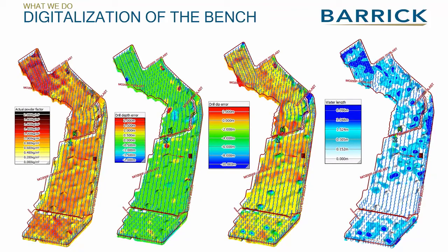And we also have a water surface of how it was on the pit. And as you can see, actually, we can have conclusions by seeing this. Between the blast, you can see that we have the less powder factor. That is because there is where the holes are more potentially falling. So with that, we can get into conclusions and work with that in order to not have, for example, boulders, or have a better improved fragmentation, and so on.